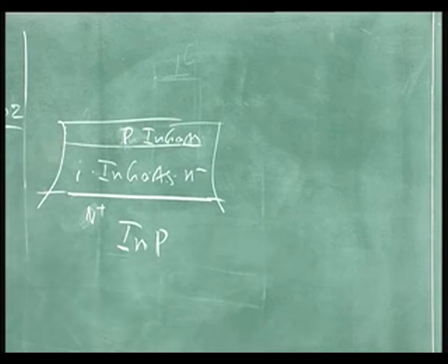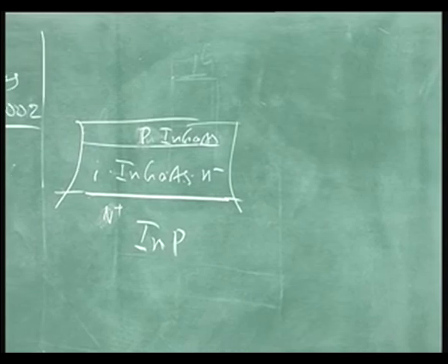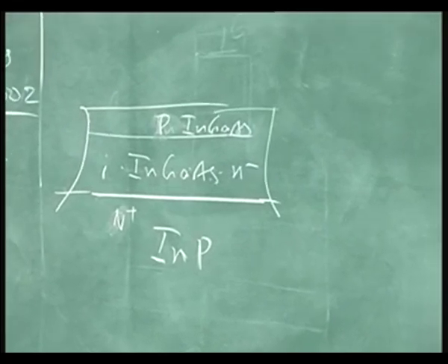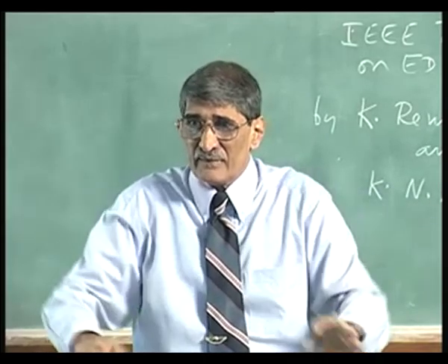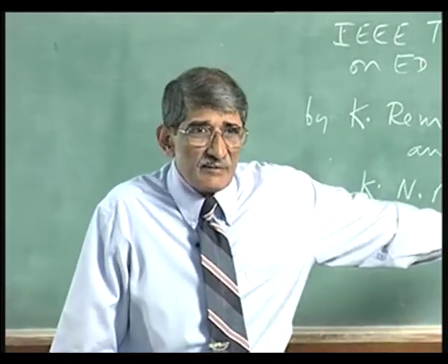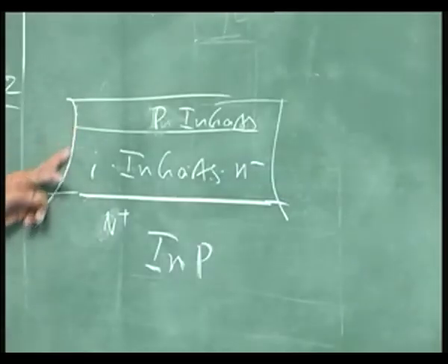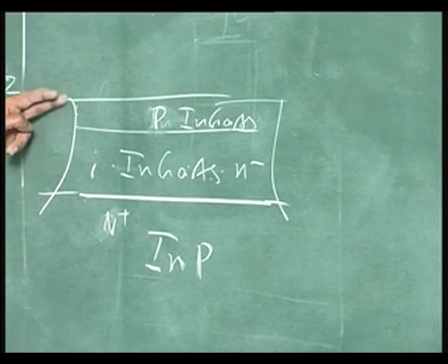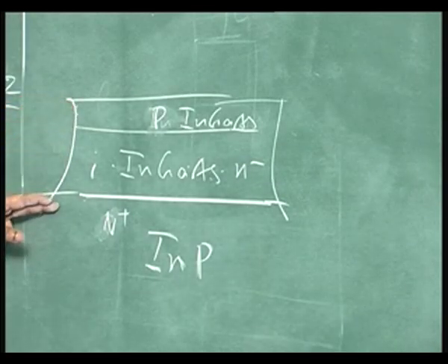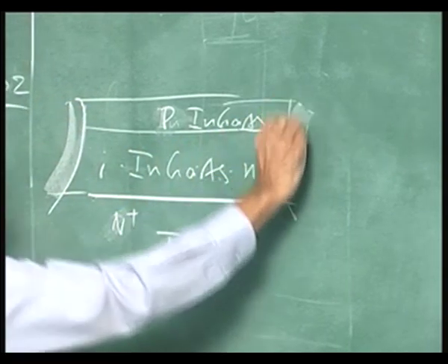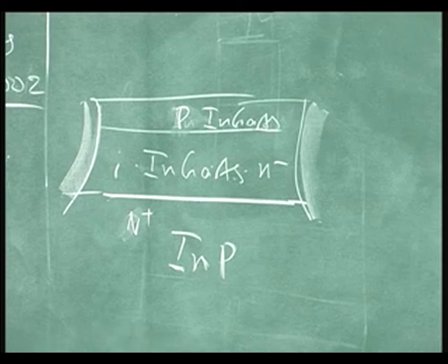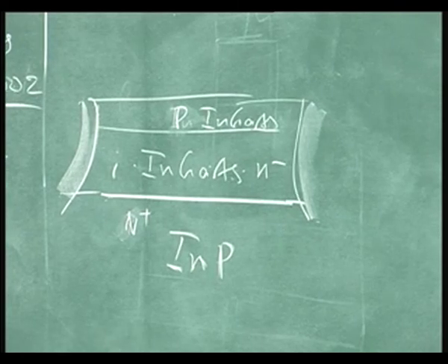When you have the junction exposed, the whole thing what you have to remember is a PN junction is fabricated using epitaxial layer, you etch it down, so that isolate one device from another one. You are on the wafer, number of devices are there, this surface is exposed. That gives rise to large leakage between the P and N layer. You passivate it, and this passivation is again ammonium sulphide which is being used.